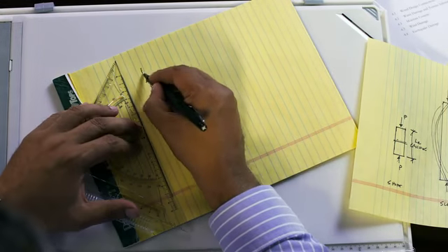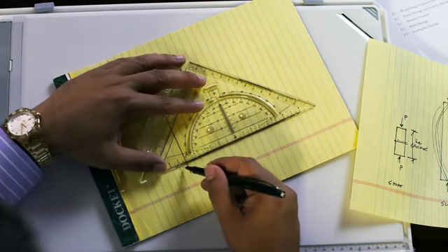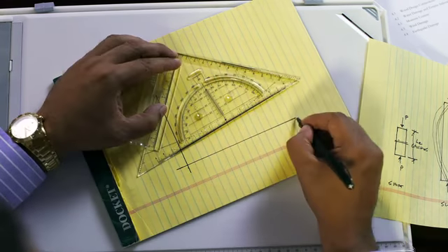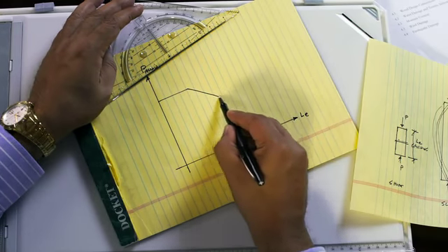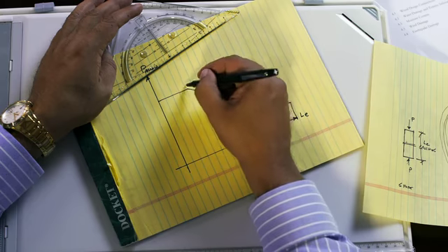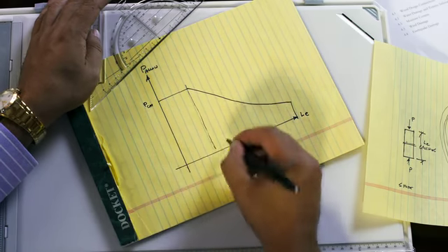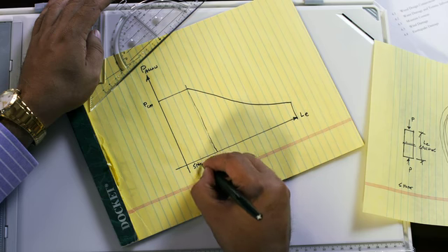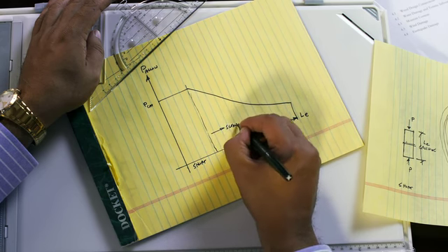You have the allowable compression load, you have the effective length, and the curve looks something like this. And over here, you get the maximum capacity when you're a short column. And when you pass this, you become a slender column.